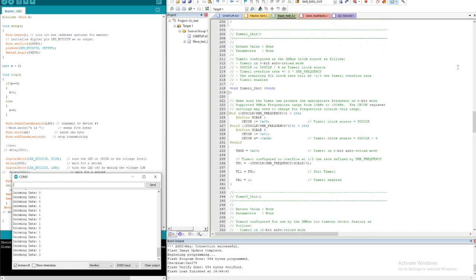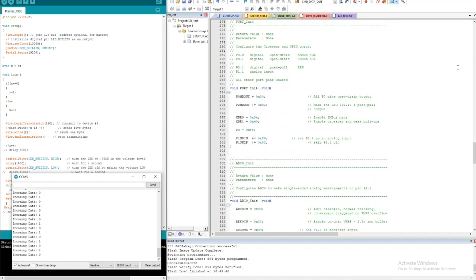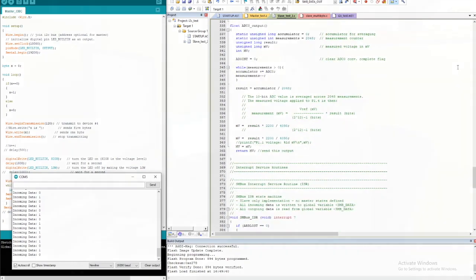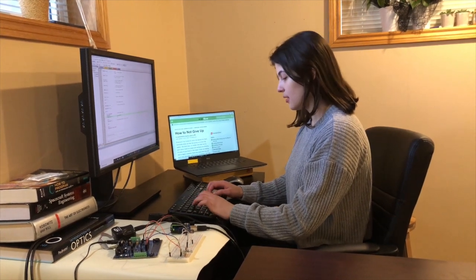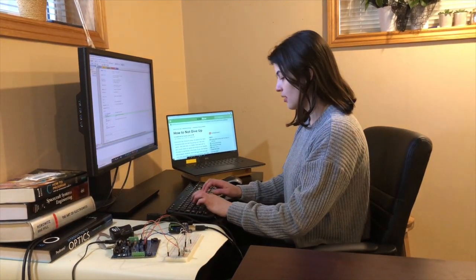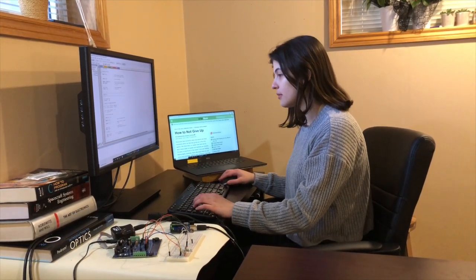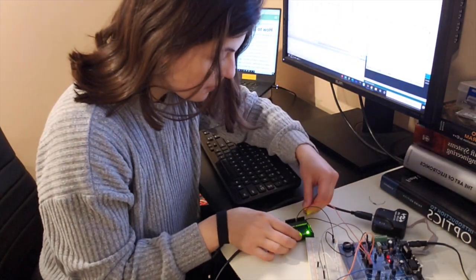Software is needed to control the laser from the microcontroller. It will modulate at a specific frequency and only turn on at certain times. The microcontroller must communicate with the rest of the satellite to share health and telemetry as well as receive instructions. The microcontroller was programmed to communicate with the satellite's onboard computer through I2C. We integrated different controllable modes of operation, which allowed us to vary the behavior of the laser beacon module.